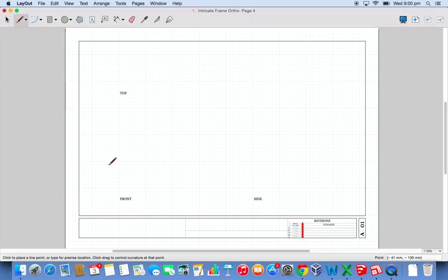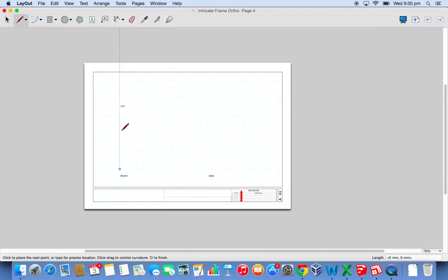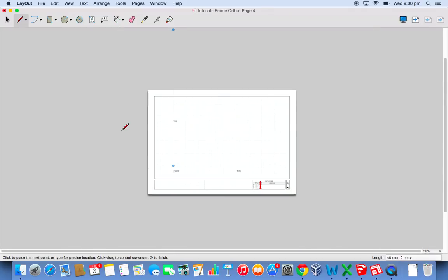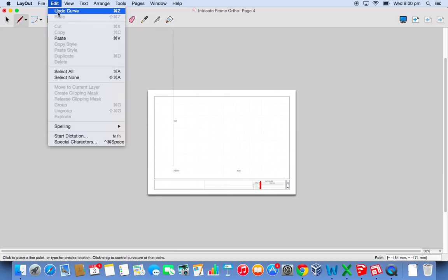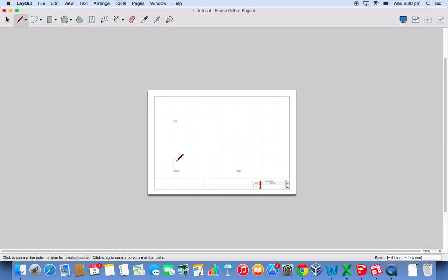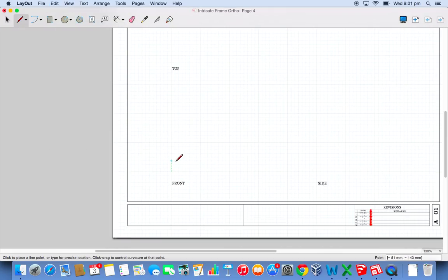So even though I have that selected, and I've done this numerous times, when I go to draw something, I'm going to draw to 274, and it just draws that line off the page. I don't know why it's selected as a scale, but I just find it doesn't draw that. So we're not going to let that deter us, and I have found another way. It just means that you have to work out the scale yourself. So we know that first line is 274.